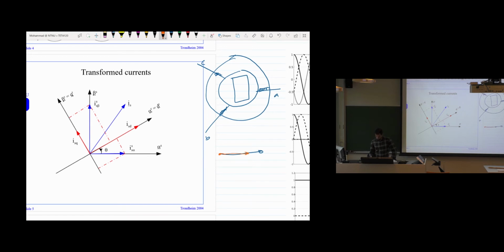It reaches the positive peak, then it starts reducing, goes in the other direction, and becomes the negative peak. So this axis is fixed in its position, and the voltage goes from 0 to max, comes to negative max, and then again goes to positive max. And if you look at it in the time plane, you'll see it's a sinusoid.